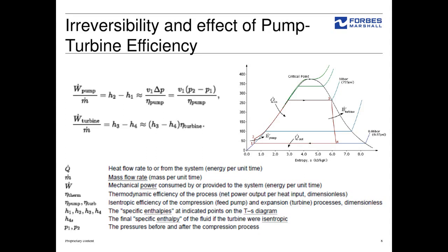So when you compress your water, I would say compress, but it's when you pump your water, when you increase pressure of your water, water is an incompressible media. So whenever you do that, there are some friction losses, there are some irreversibilities, there are some heat losses which cannot be recovered back. And that's why in process 1 to 2, where pressure is increased, there are some pump efficiencies which actually play a key role and this isentropic process deviates slightly on the right side.